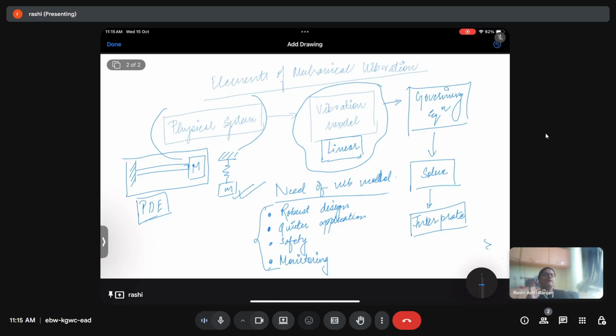We made a system. We saw how it is operating. We take the vibration data and we see that, okay, this is the data that we get for a healthy system under these conditions. Now, after 10 years, 20 years, I want to check how the system is still behaving, or whether there is any kind of fault inside the system. So after that, we again set the system under the situations that we considered earlier for taking the data of a healthy system.